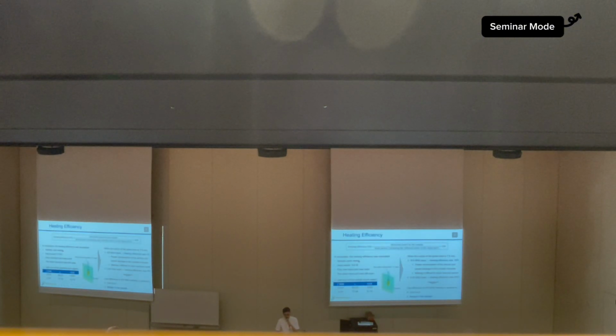We can calculate heating efficiency using a simulation software called CST Studio Suite. Here is the definition of the heating efficiency: absorbed power by the sample divided by input power, excluding the reflected power at the input port.